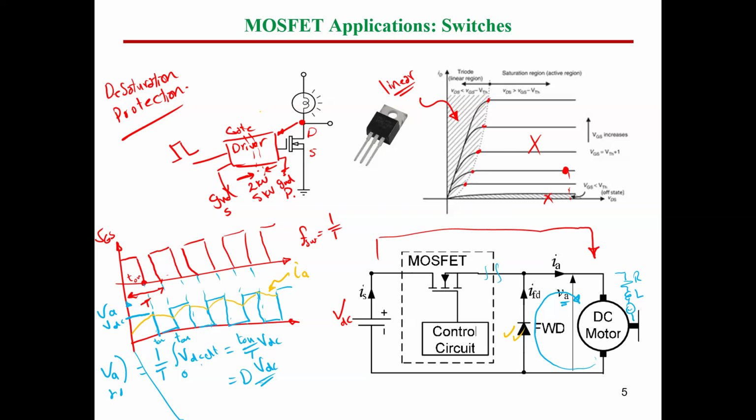Also, something new is regarding the gate driver. I believe you have never heard about this before, but if you are going to make this circuit, you have to design a gate driver. This is one of the important benefits you will understand if you make this project. In most projects, you will have gate drivers because by the end you will operate a MOSFET. So by the end, you have to use a gate driver.